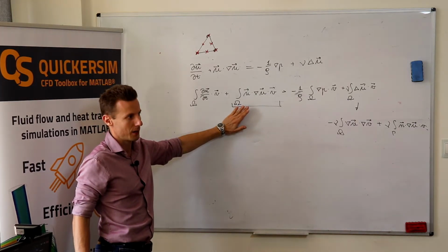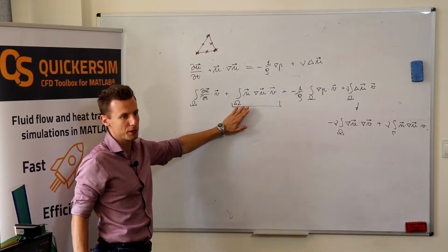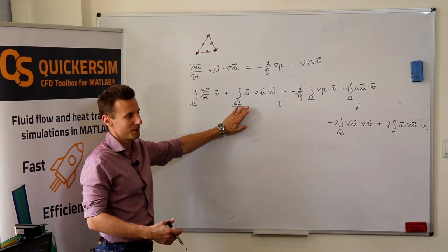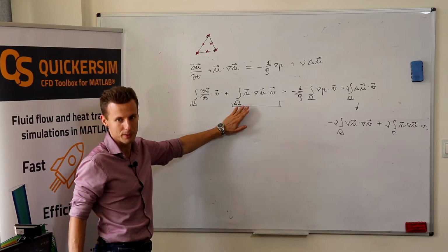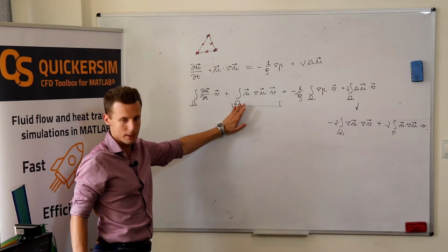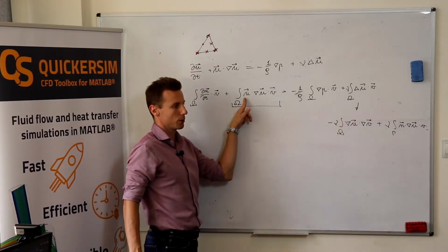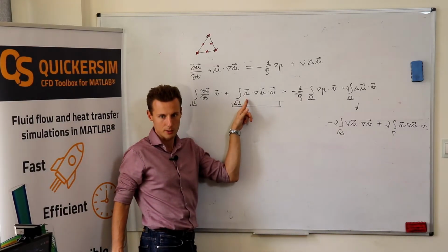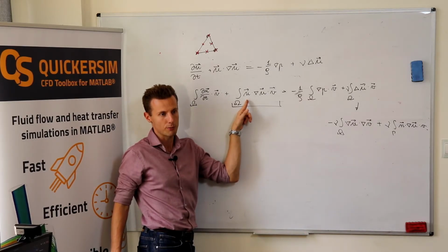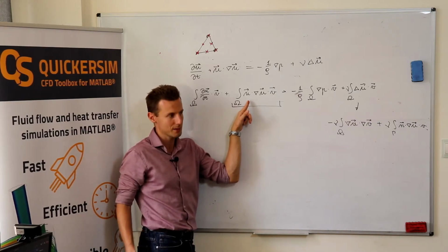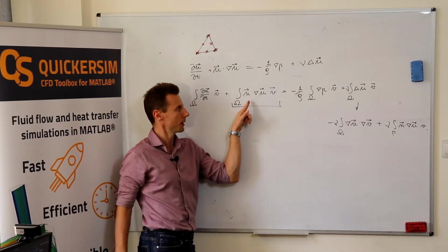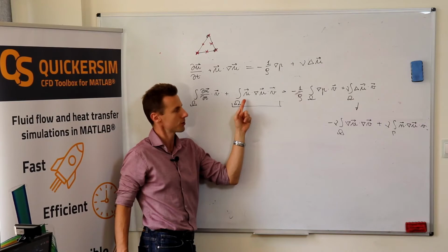a nonlinear equation. We typically solve nonlinear equations by solving a whole series of linear subproblems. So when assembling the matrix for solving the Navier-Stokes equation, you usually need to assume the convection velocity. Basically take it usually from the previous step of the iterative process, or you might have other guesses. I will talk about that at the end of my lecture.